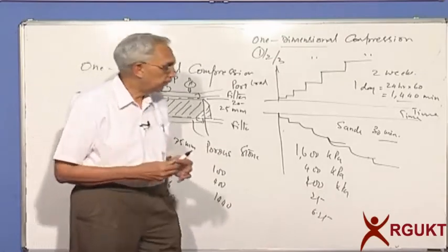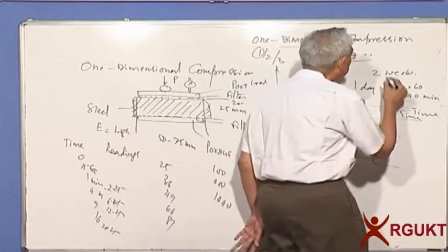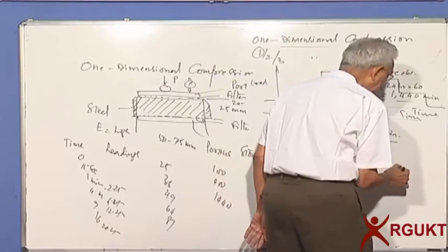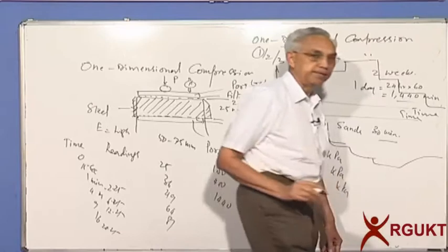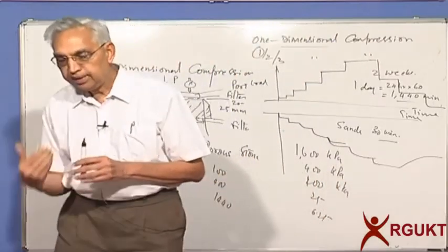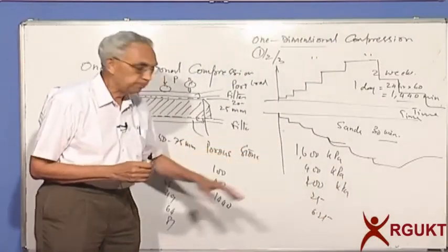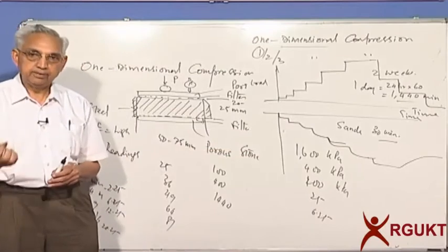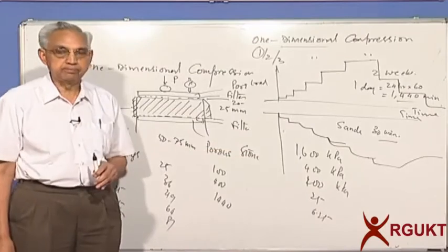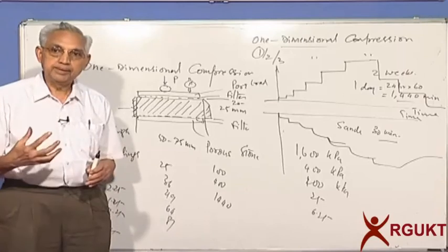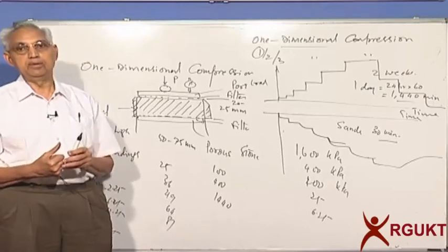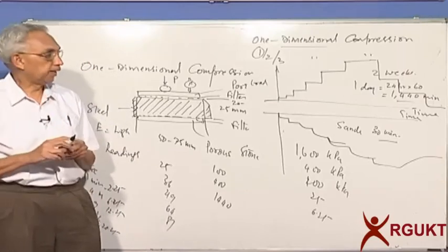So what you then do again, there will be a slight recovery. Soils being inelastic, even if they compress by about 5 millimeters, the recovery would be less than 1 millimeter for this sample. That is because once the grain goes into a lower position, it will not bounce back.